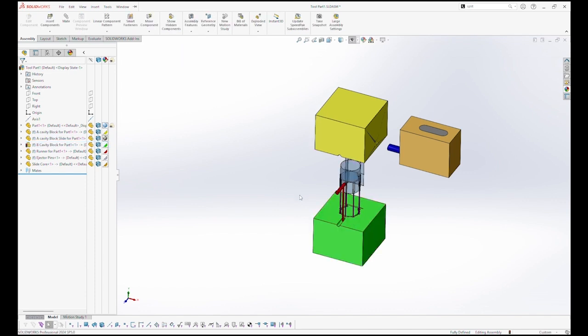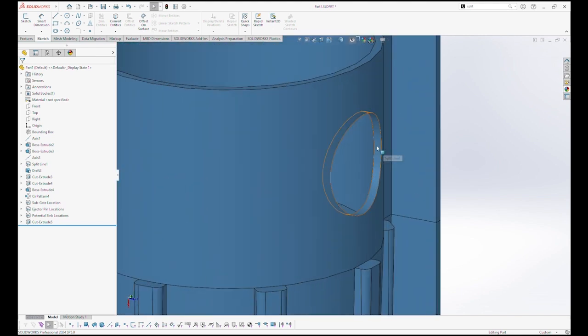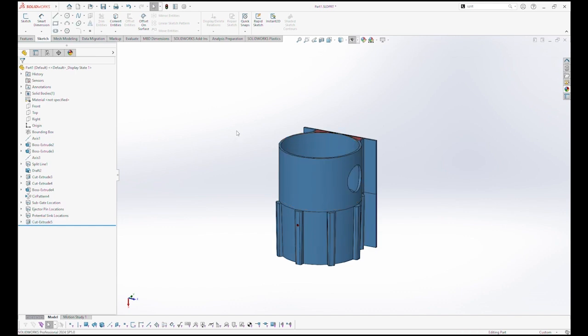And anytime that you can pick a parting line on your part that is simply an open and a close, that's your simplest, most cost-effective methodology to do injection molding. It's when you introduce features like this hole, which has an axis that runs perpendicular to the open and close axes, or the parting line axes, that you start increasing the tooling cost and making the tooling and the part pricing just a little bit more expensive.